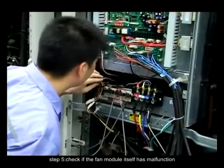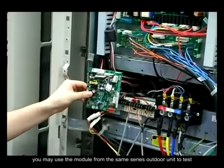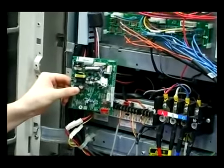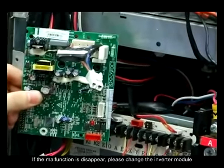Step 5. Check if the fan module itself has malfunction. You may use the module from the same series outdoor unit to test. If the malfunction disappears, please change the inverter module.